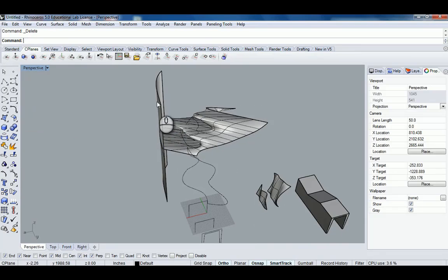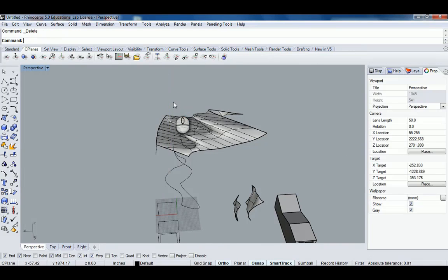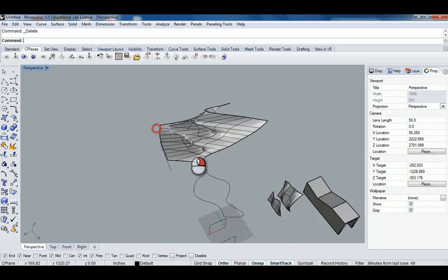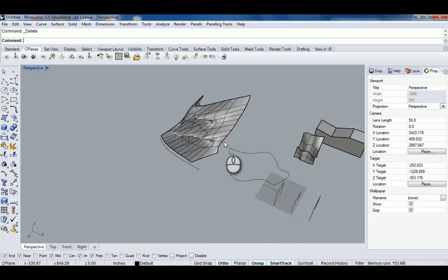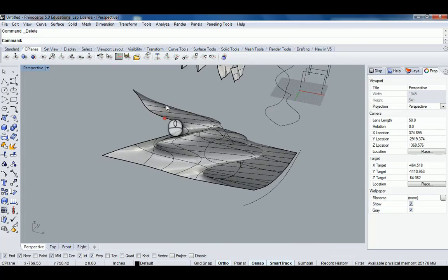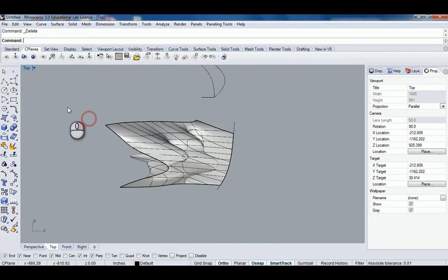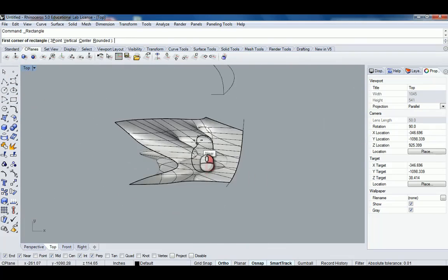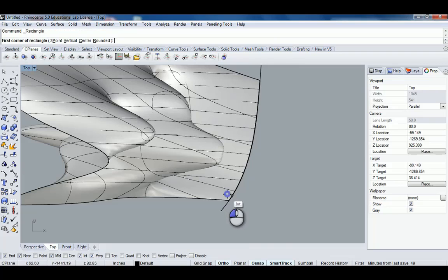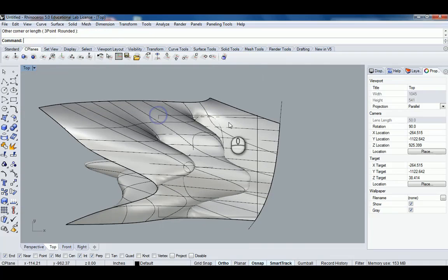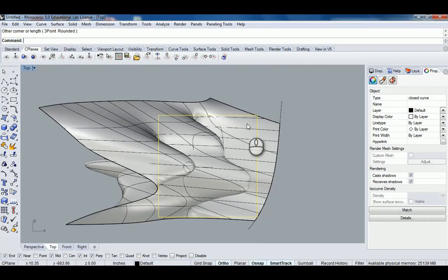Generally, the split or the trim command would probably be the best way to do it. Say you did use patch and it was fairly successful in creating a landscape or something, but it has these weird twisted edges like you're talking about. In plan, I would draw a box so it at least is something regular. Then after you've extruded it, you can trim it. Okay.